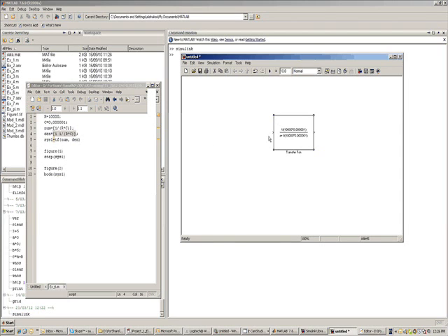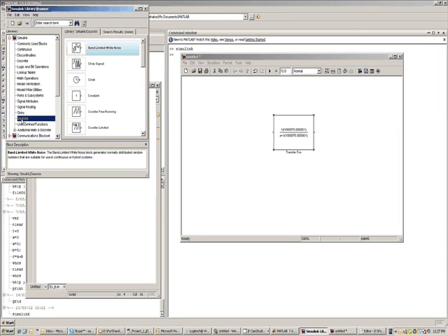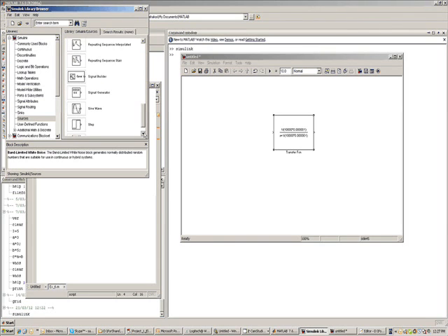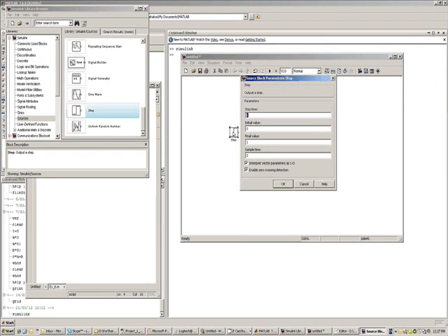How to do that? We have to apply a step as its input. This is the input from where the signal is given to the block, and the output comes from here. So all we need now is some way of giving the input to the system, and then some way of looking at the output. If we go back to Simulink, in the sources library, if you go down, you'll find the standard step signal.